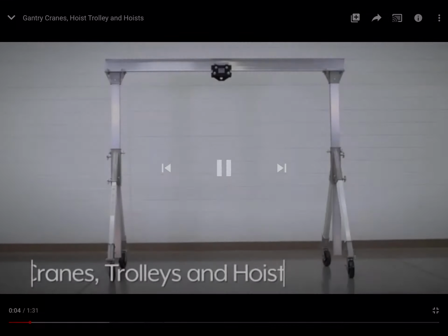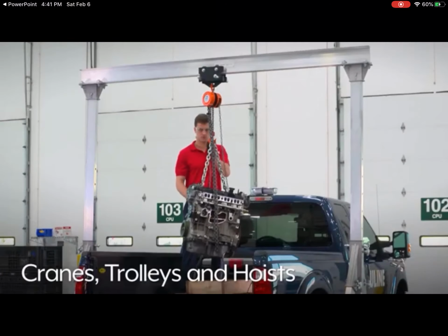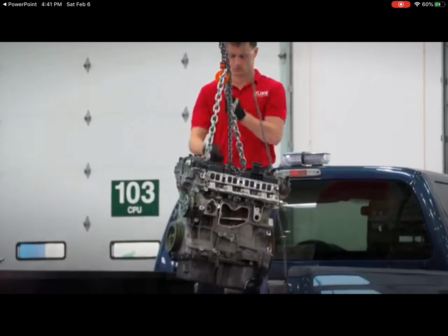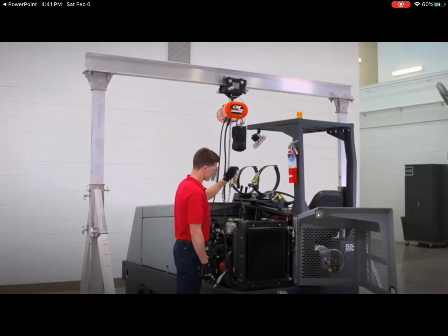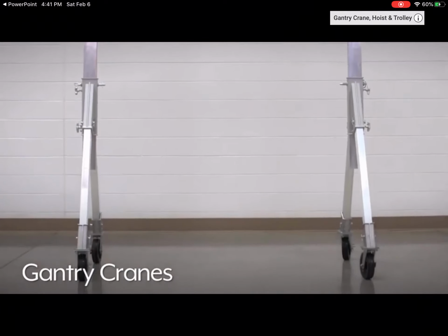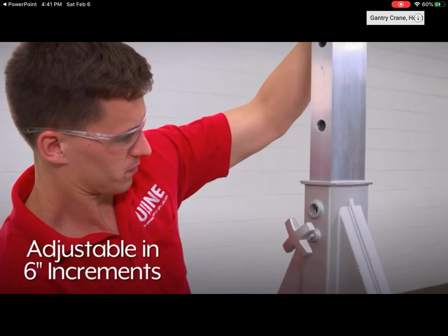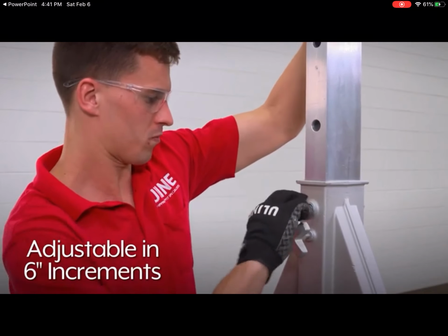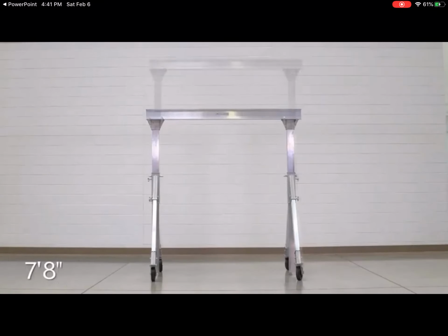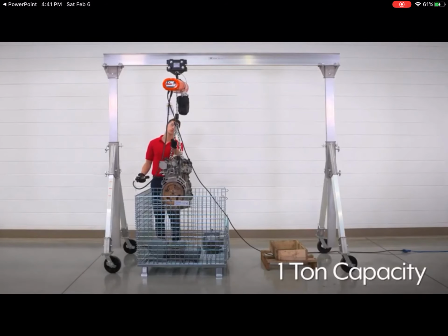U-Line gantry cranes can be used in conjunction with hoist trolleys and an electric chain hoist or hand chain hoist to hold and position heavy motors, generators, or machinery. Gantry cranes' lightweight aluminum construction allows for easy setup around job sites. They can quickly and easily adjust in height in 6-inch increments, from 7 feet 8 inches to 10 feet 2 inches, and feature a 1-ton capacity.